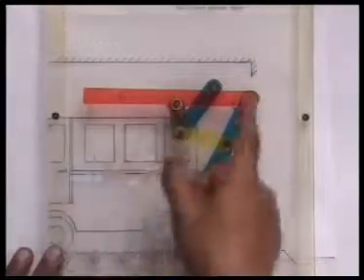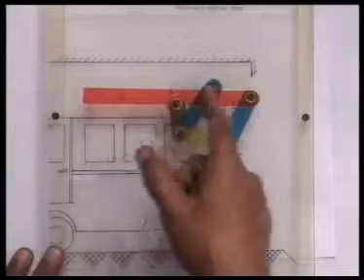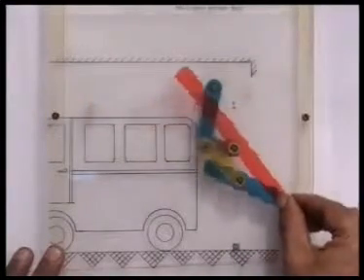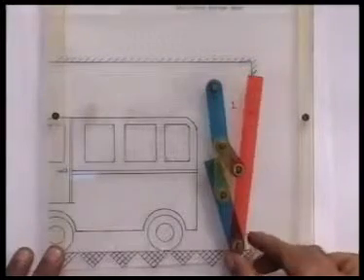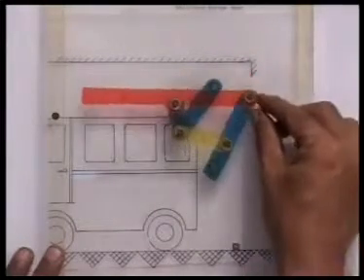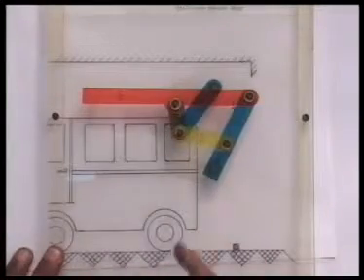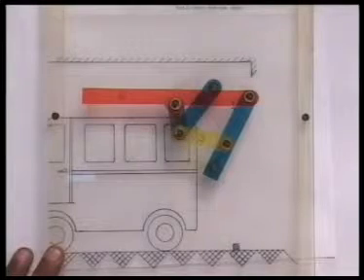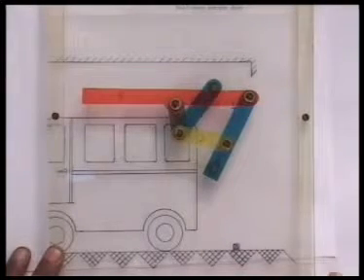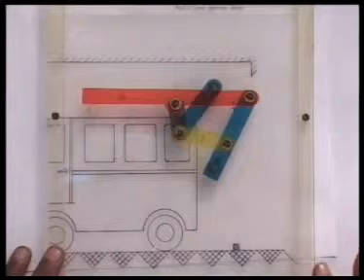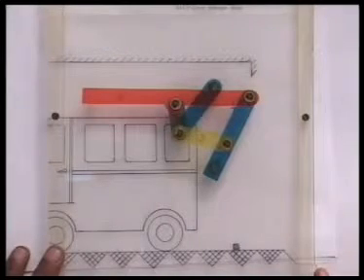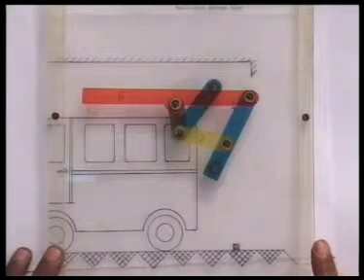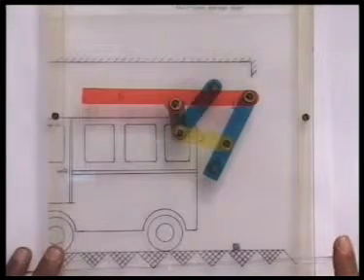Thus, the motion of this garage door board is almost horizontal and then suddenly falls to the vertical position. And such a movement is not possible by using a simple 4-link mechanism with the door board as the coupler. So we go for this 6-link mechanism. And now we shall give the details of the design of this 6-link mechanism and determine all the kinematic dimensions by applying the multi-stage synthesis procedure that we have learnt earlier.